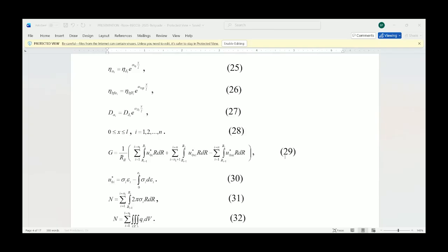The strain energy release rate solution determined is checked by an approach according to which the strain energy release rate is the derivative of the rod complementary strain energy with respect to the delamination crack area. This approach leads to a strain energy release rate which matches the strain energy release rate found by the solution derived in this paper.